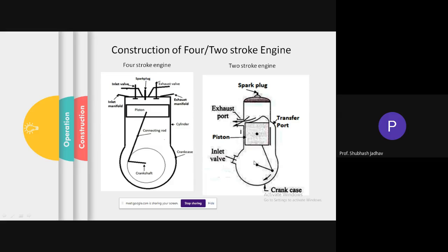Whenever the pressure is higher, more than atmospheric, what will happen? The pressure will be acting on that particular plate, and that will press the plate on the surface of the wall. Therefore, there will not be any gap between the plate and the hole, and it will be closed. That means whenever there is a negative pressure over here, this is going to open and allow things to come in, and whenever the pressure is higher over here, it is going to be pressed and closed. So that is the function of the reed wall.